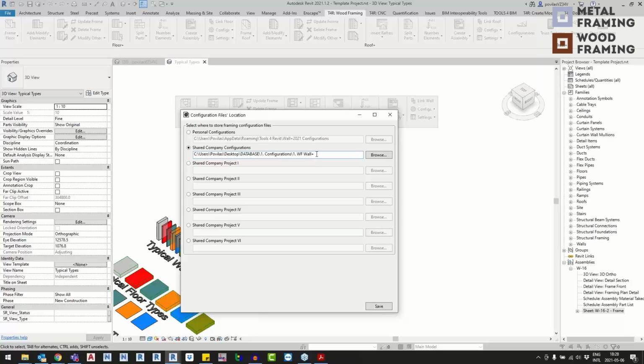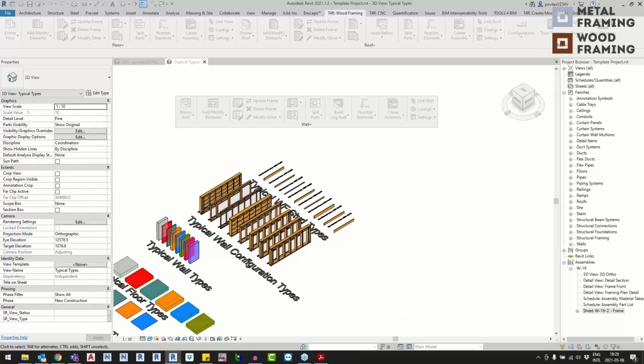And for some reason, if the software wasn't able to detect those configurations, the issue may be that there are two things. So the file path has become too long, and the software is just unable to read the file path. So just one thing to be aware of when you're using servers, just make sure the file path isn't too long, or if configurations are not recognized, look at the file path and try to reduce the number of elements or digits or letters.